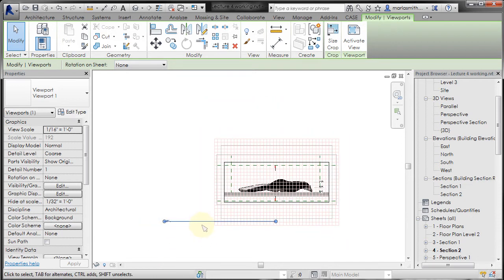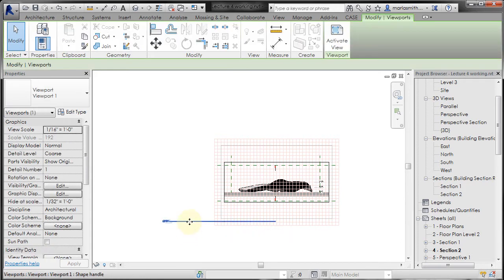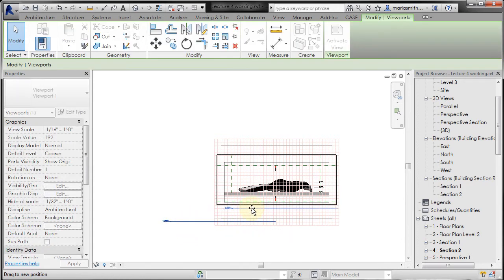It places that view title in the area where the view was first placed, and since we had it off and we were moving things around, it got sort of disconnected. So to move that view title, click off of the view title itself. So I'm going to left click on nothing, and then left click on just the view title. Move it into place. Okay.